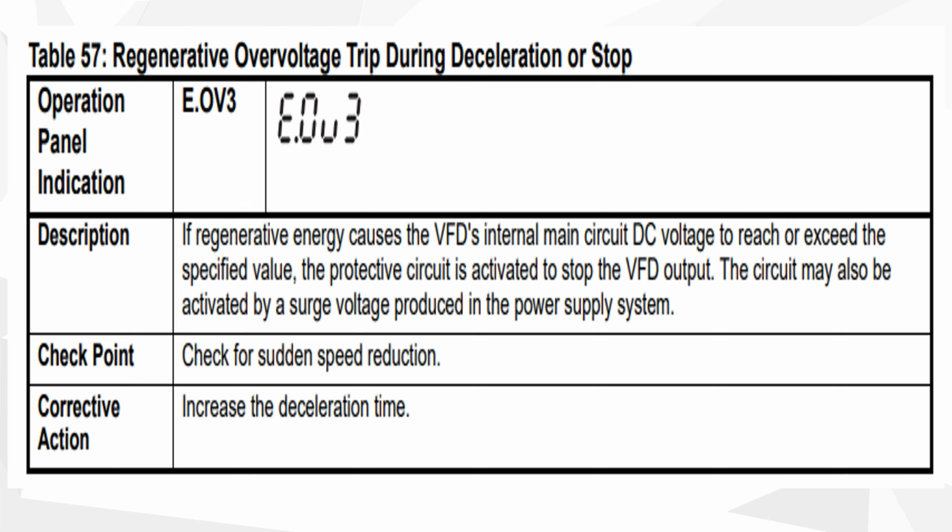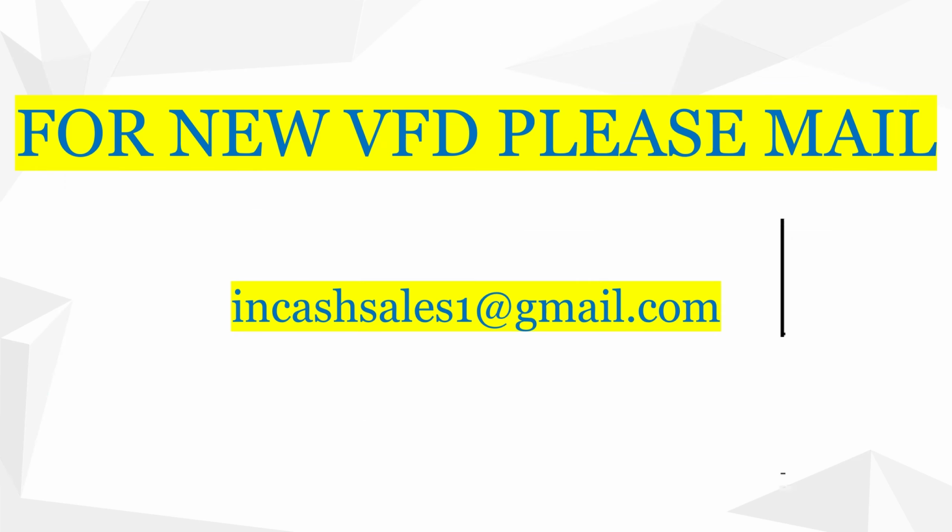Okay, so to resolve this, the manufacturer created this error. First we have to increase the deceleration time, because it will take more time to stop. So we have to increase the deceleration time to resolve this. And if it was working fine and suddenly this is happening, it means there is some issue with the power card. In that case we have to repair the power card or replace the VFD. This is the solution.